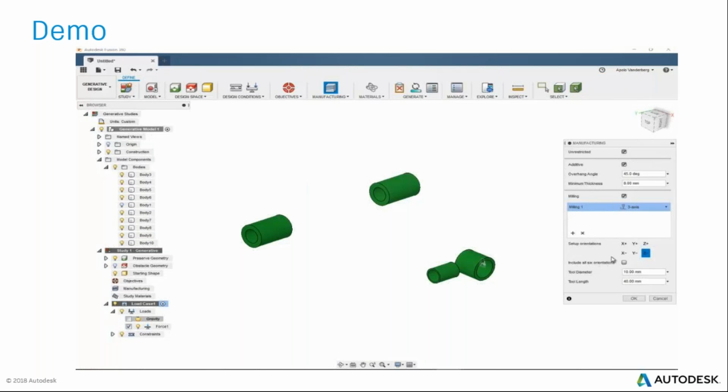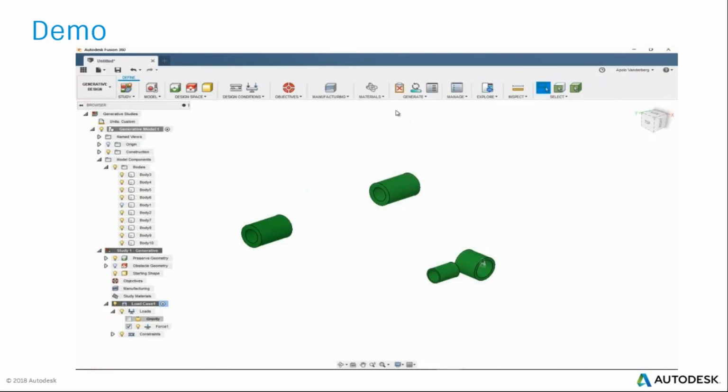Here, just to go back to it, during the setup process, this is where you're picking those manufacturing methods. When I did this video, I need to go back and update it to include now the die casting and 2-axis cutting. But this is where you're specifying what the minimum thickness is for your parts that you can print, and what the overhang angle is. As you include this, we will, again by default, assume we're going to do 3 outputs for additive in the positive X, Y, and Z directions from the build plane.